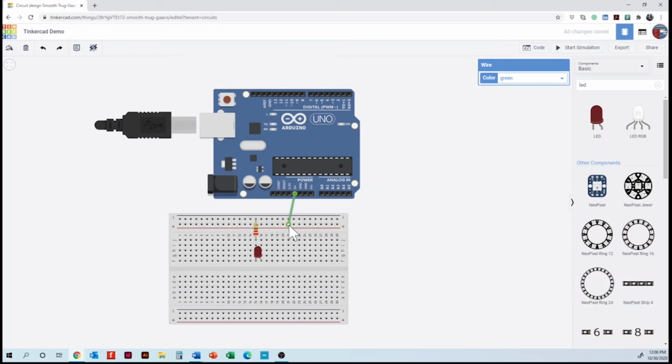And if you see there, when you connect the 5 volts to the breadboard, you will see the pins in green. All the row is gonna be connected horizontally. So it doesn't matter if you place 5 volts here or here or here. I mean, the connection is gonna be always 5 volts.